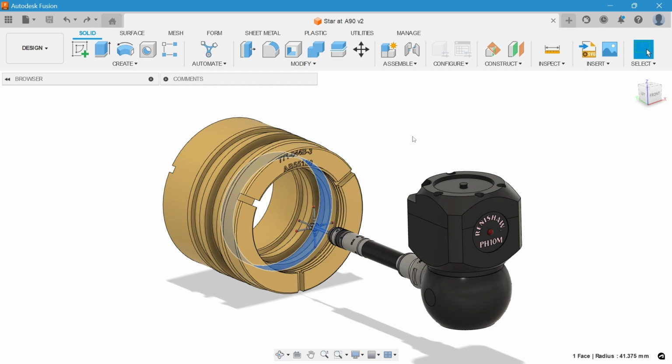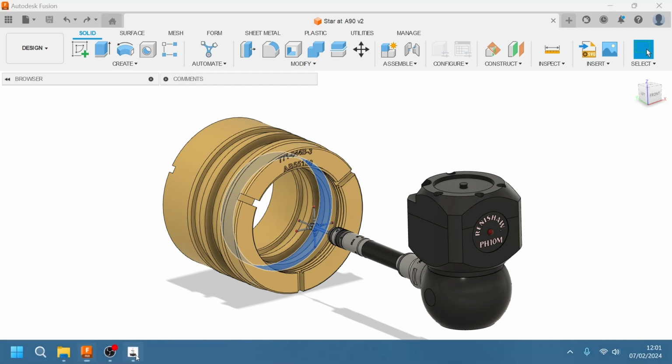an undercut cylinder. So in the previous exercise, we increased the pre-travel, which is an easy method for avoiding that collision. Only it does add cycle time due to the moves being at the slow controlled probing speed. In this example, we're going to use move wires, which are far faster, only that it's slightly more complicated for inserting those moves. So let's switch over to Aberlink and get the measurement.